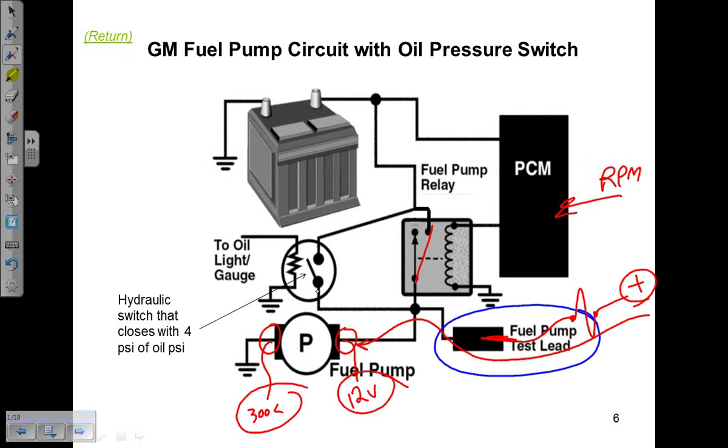So it's nice. If the car comes in, again, it doesn't start, and you have no fuel pressure, and you jump this circuit, and now you have fuel pressure, now you're going to focus up this way. But if we still have no fuel pressure, you're definitely down here, but it's nice because you don't have to crank the engine over to do it. So along those lines, I want to show you one more.